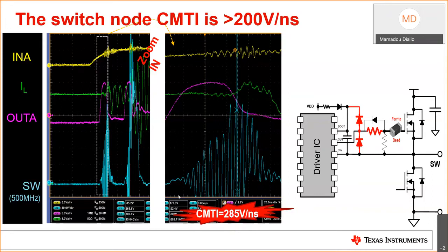And if you see here, what's happening is because the high side is referenced to the same switch node, exceeding the max DVDT on that switch node will cause the high side channel to misbehave. Common ways to deal with this is implementing a slower DVDT by increasing the turn on resistance.